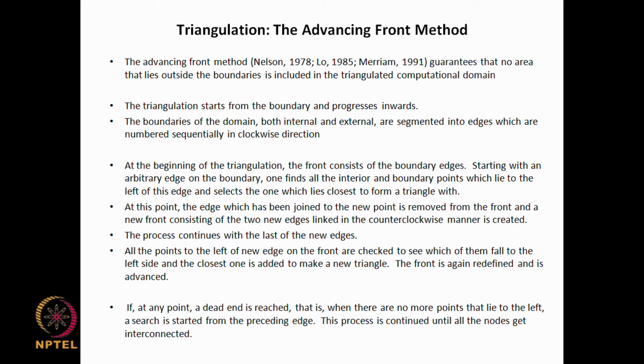One of the conditions that we have said was that there should not be any new area that lies outside the computational domain included, and this algorithm guarantees that. The triangulation starts from the boundary and progresses inwards, so that we do not have this problem of including external area. The boundaries of the domain, both internal and external, are segmented into edges which are numbered sequentially in a clockwise direction.